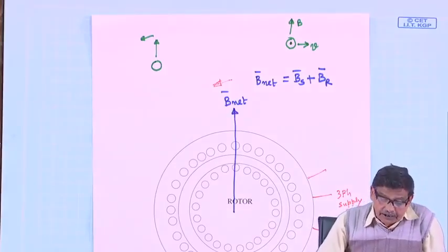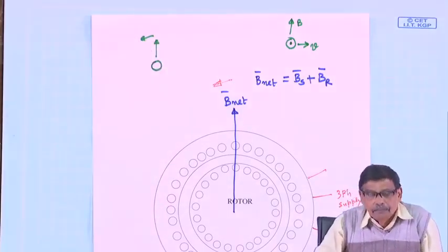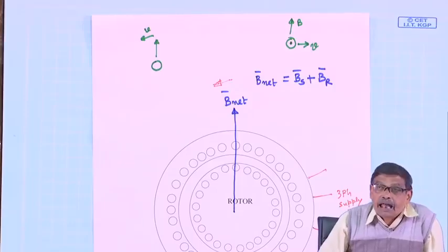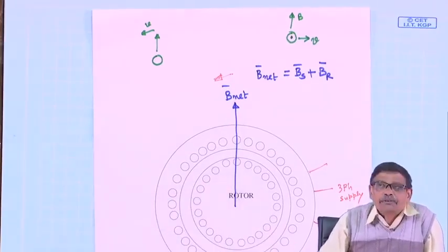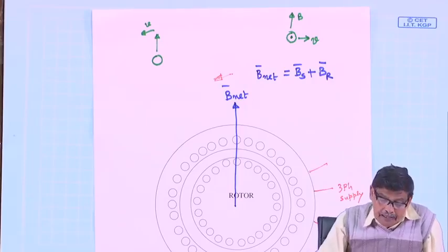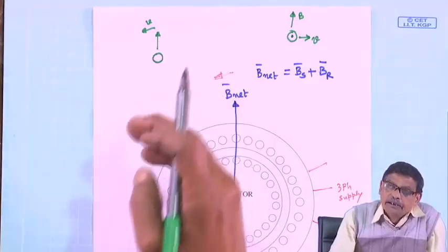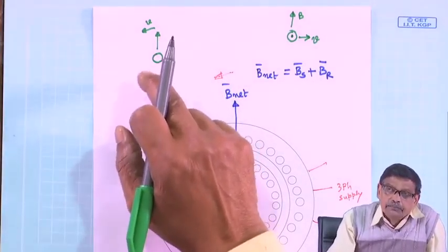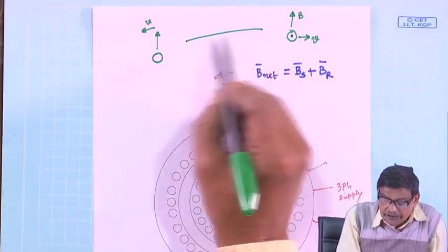In which way different? The conductor is not moving and b is moving with a velocity, say v, tangential velocity, not RPM, ns, etc. v I have to calculate. But fortunately what happens is this, the relative speed is v. To know the correct polarity of the induced voltage, you translate this problem to this.